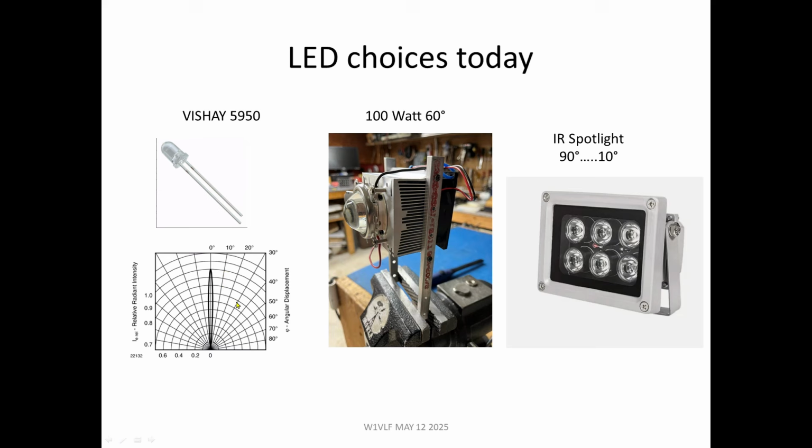And what do I mean by that? By the 50% power line, it's plus or minus 3 degrees. So all that power is condensed into 6 degrees instead of plus and minus 30 degrees. You can do the math on that and find out how much more intense that is. It's very intense.